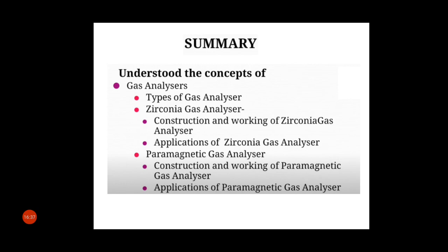Then we have studied two different types of oxygen analyzer and their working principle. In an oxygen analyzer we have a sensor. The sensor produces a small millivolt output which is directly proportional to the oxygen detected in the sample, and this sensor is an electrochemical fuel cell.